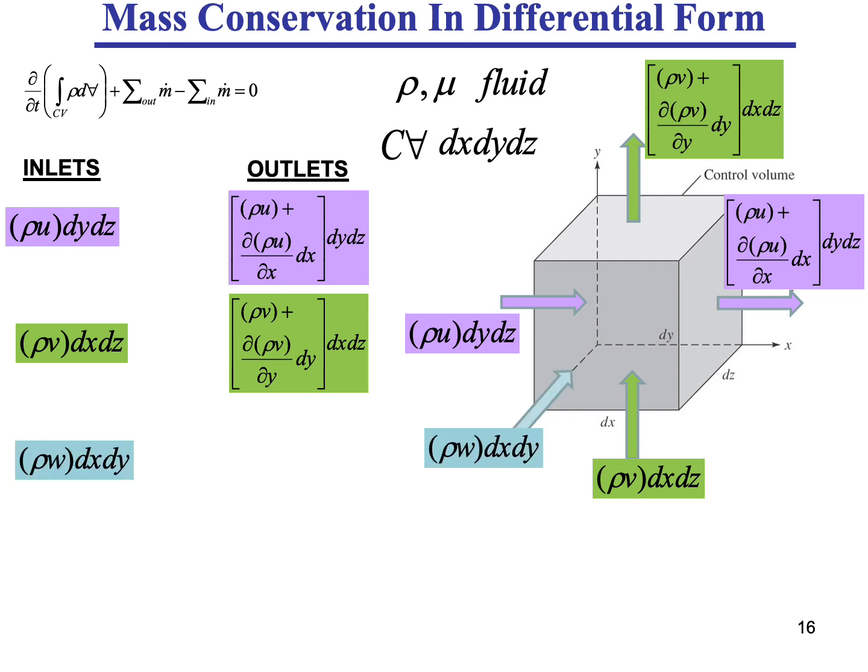And we do the same thing for the third face. This is the z face. You notice that I'm using the axis perpendicular to the face to refer to this particular face. So this is the face z, and that's the face z at z plus dz. Here at face z is the velocity in the z direction, w, multiplied by density and by the area dx dy. And what comes out is rho w plus this extra bit of mass flow. So here we've done the flux terms, in and out. It's out minus in, so let's subtract that minus that.